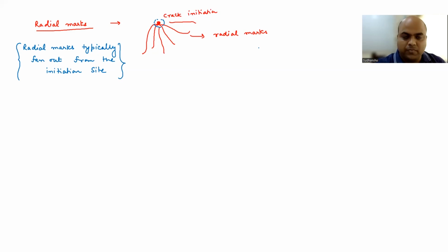Okay, so overall, for the fracture mechanisms, we started by talking about ductile fracture mechanisms. I introduced the concept of dimples, etc. Cup and cone fracture, rupture, those are the ductile fracture mechanisms. Today, I discussed the brittle fracture mechanisms or cleavage fracture, and its nucleation in terms of either a pre-existing crack or local plasticity.